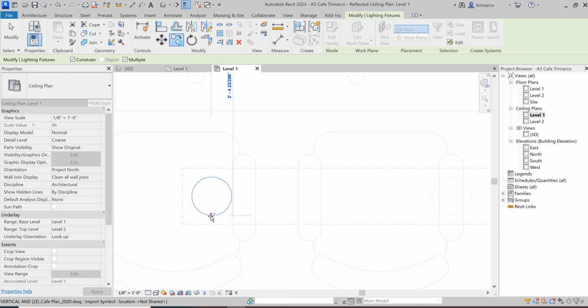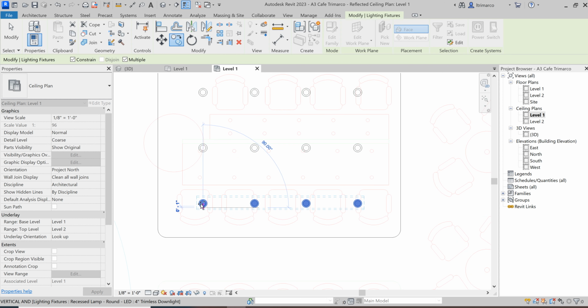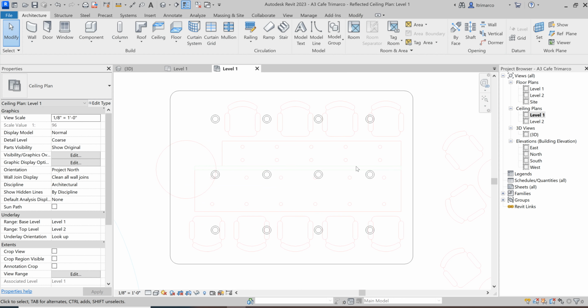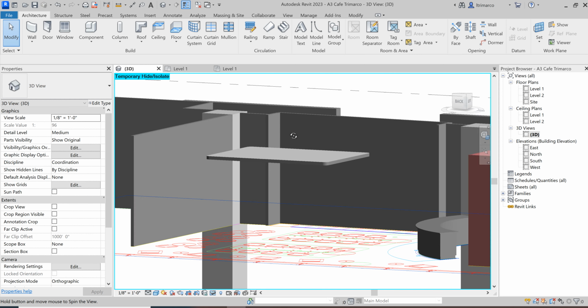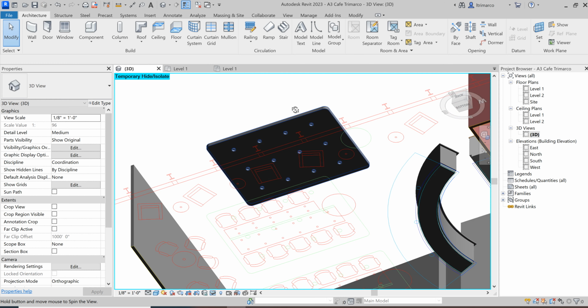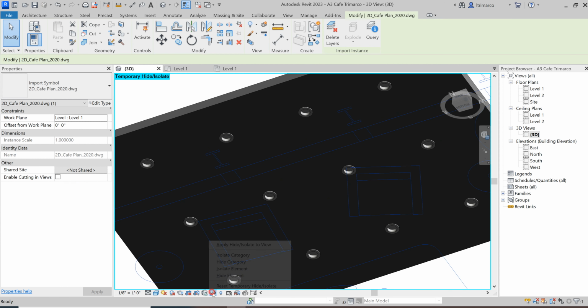And again, double arrow, it basically means it's vertical and nearest. And you'll see a little flag pop up for it. It doesn't show well on video, I should say, as I'm demonstrating this, but it is snapping a little bit. So there is kind of a little bit of help. I'm going to save where I'm at. I'm going to last jump into a 3D view, and I'm just going to orbit myself upside down and make sure that I see openings. Again, if you need to turn off your CAD drawing, go ahead and turn that off.